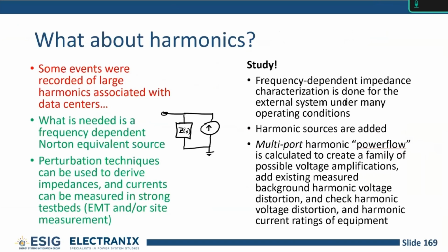Or more likely, you're going to measure this in a lab. So you get harmonic measurements from each of the components in the load from a lab, and then they can give you an aggregated model of the load for harmonic purposes.